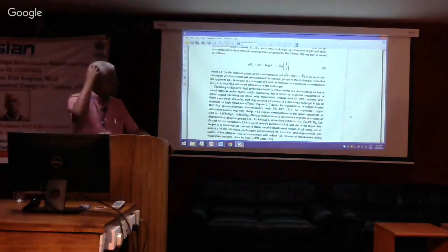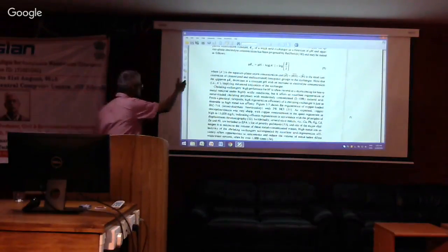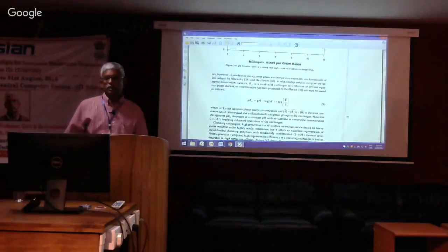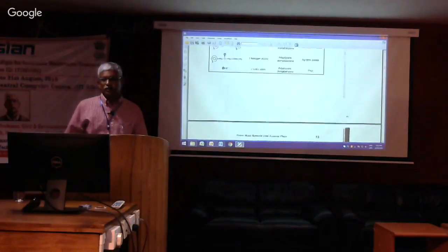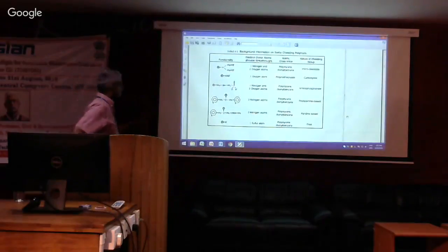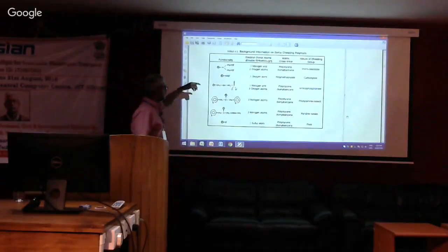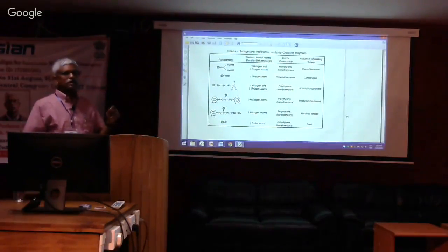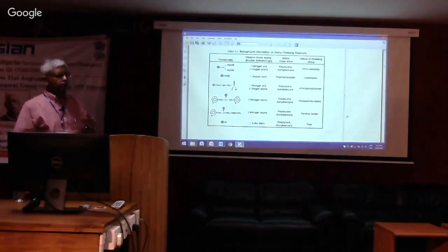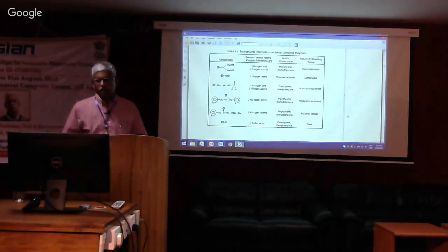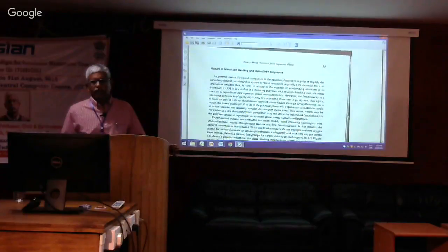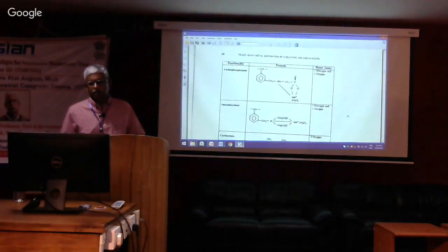So we can use this formula to get a sense of our pKa. Because keep in mind, pKa of a resin with carboxylate functional group will not be the same as pKa of acetic acid. It will be close, but it will not be the same. Okay? So we need to use this formula, and we have to find that through titration typically.